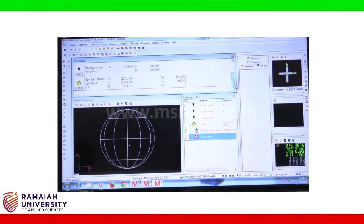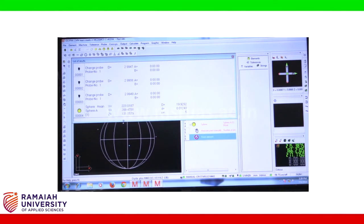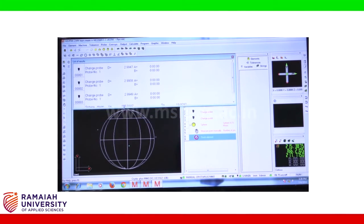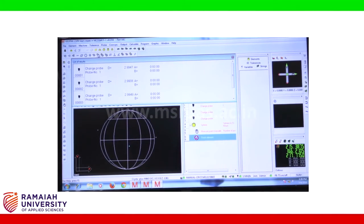So for this sphere, this is the command, and you can see 0.004 is the program code, and these are the XYZ coordinates. Similarly, one can measure other geometries like cylinder and circle using these commands.